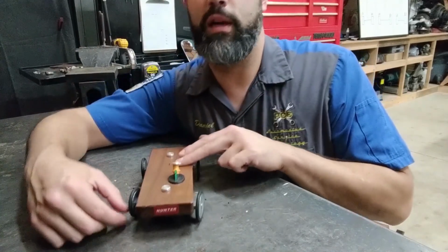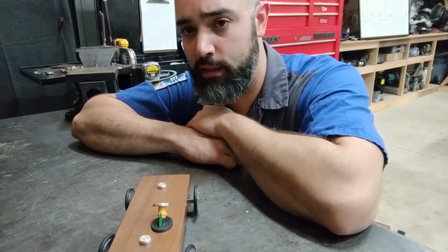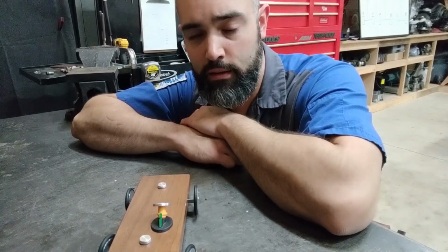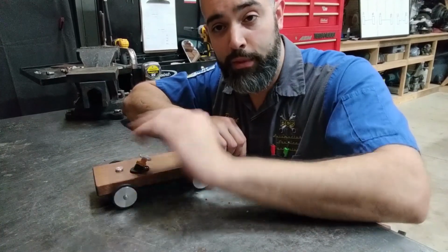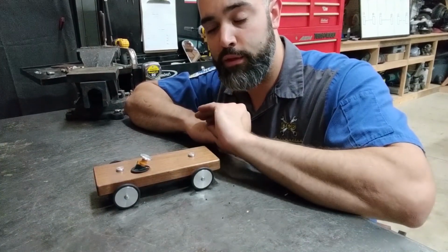If they were moving along and the tire's locked, they would just continue going in the direction they were originally traveling. Now that's not as bad in the front as it is in the rear. So anti-lock brakes help the driver avoid an obstacle or a collision during a panic stop situation.